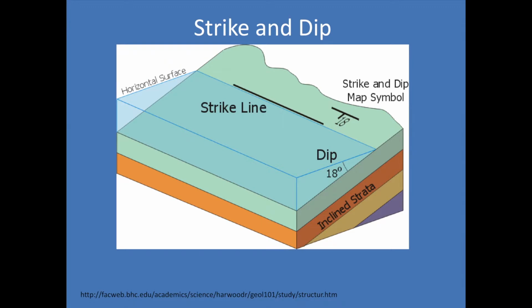So generally water flows downhill, and so the direction that those strata align with, that's also the direction of the regional groundwater. You'll see that the flow and direction of groundwater is also dependent on specific and localized changes in the geology, as well as the connection to the surface hydrology. But regionally speaking, groundwater flows in the direction of the geologic dip, which in our case is to the southeast.